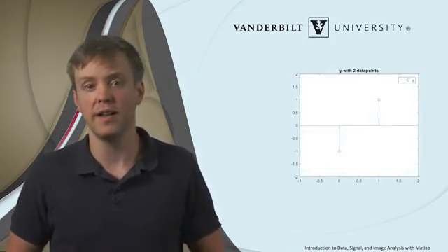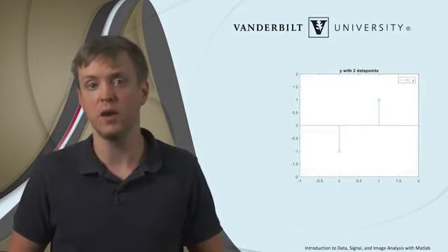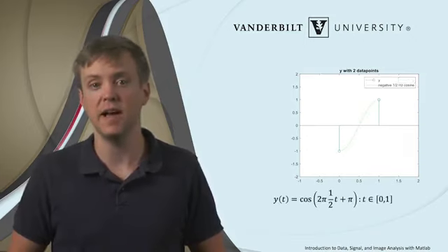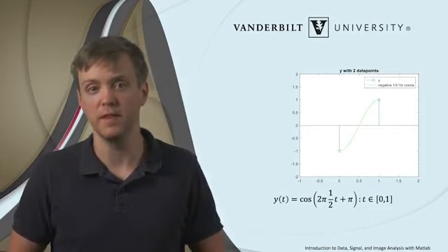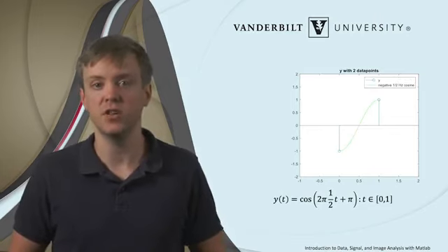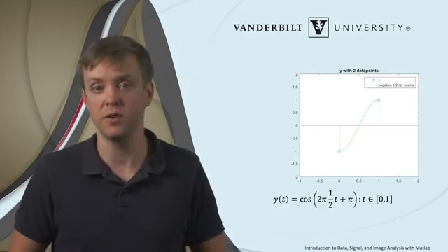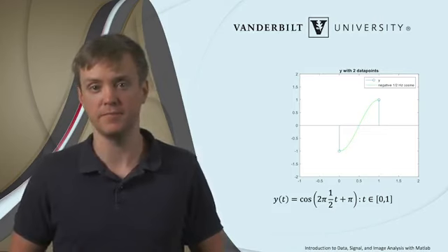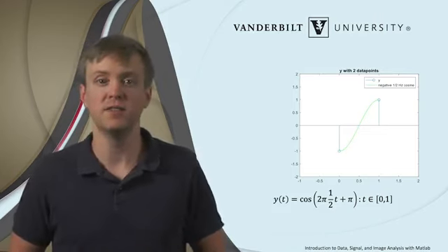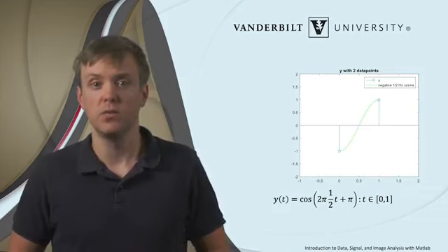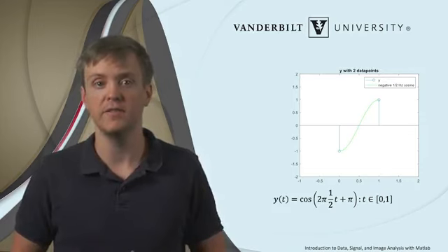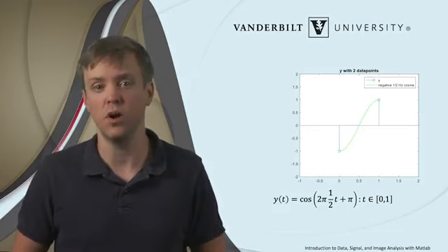First, we have a signal y that is equal to minus 1 at time 0 and 1 at time 1. We can easily define a cosine that passes through these two data points. Our FFT would tell us that for a cosine of frequency fs over 2 equals 1/2 hertz, we would multiply it with an amplitude of 1 and phase shift it by pi. The cosine itself is a continuous function. We can see that using half an oscillation of the cosine, phase shifted by pi, the value of this continuous function is equal to y at discrete times 0 and 1, where y is defined.